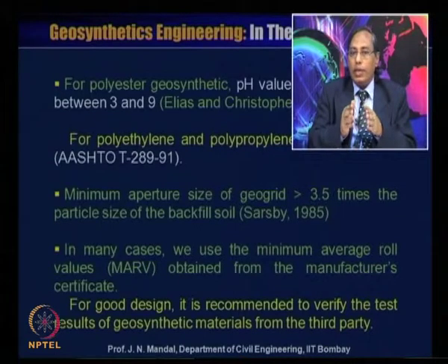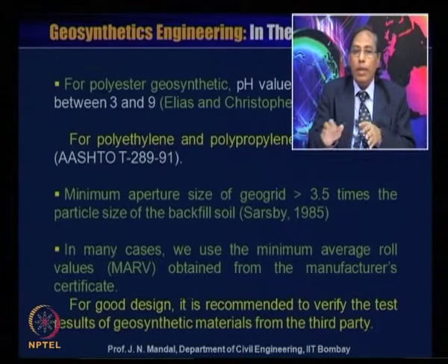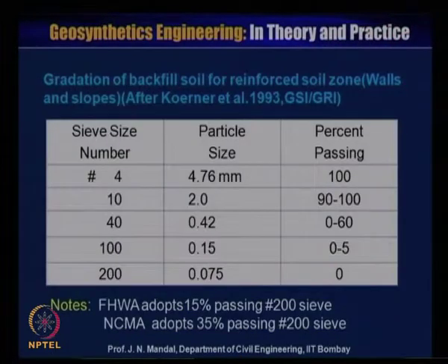In many cases, we use the minimum average roll value MARV obtained from the manufacturer certificate. For good design, good construction, it is recommended to verify the test result of geosynthetic material from the third party. Gradation of the backfill soil of reinforced soil zone, wall slope after Koerner 1993, GSI and GRI.